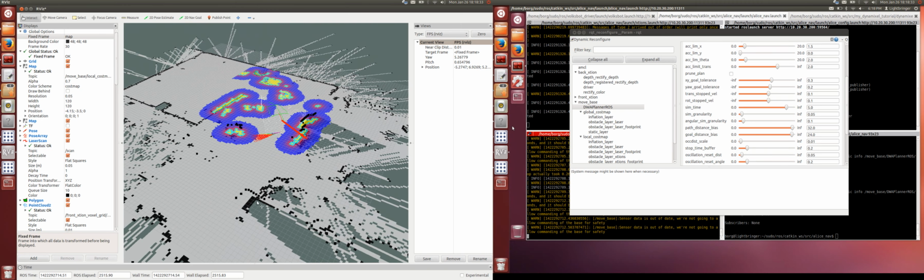The other thing that was very important was the sim time. Sometimes 1.7 is not really good, sometimes it needs more time. Like you see, the more you let the sim period go, the more the trajectories will roll out, and it can get out of deadlocks sometimes more easily. One other very important thing that I found out was the cost estimation: the path, goal, and oscillation distance.